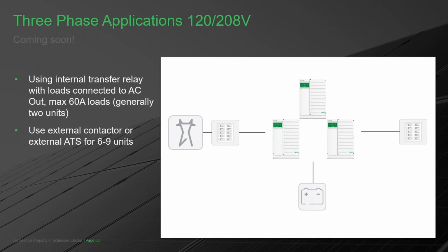support 3-phase loads. What if I need more power? So then I can add a second inverter to the phase. So now what I have is a master and a slave of each phase. When they are together, they will work as either 3 or 6 units as a single unit. This is very important and actually has to do with UL listing. If there's anything wrong with one of the phases, then the whole system disconnects from the grid.